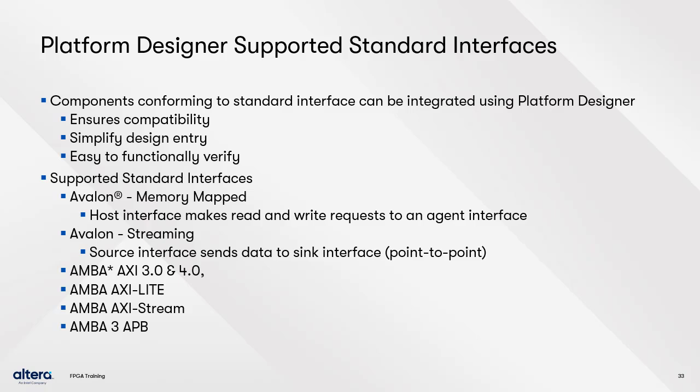This includes Avalon memory mapped interfaces, where there's a host requesting reads and writes from an agent. There's Avalon streaming, which is meant for point-to-point high-throughput applications, and there are many ARM AMBA interfaces including AXI3, AXI4, AXI-Lite, and Stream, as well as APB.